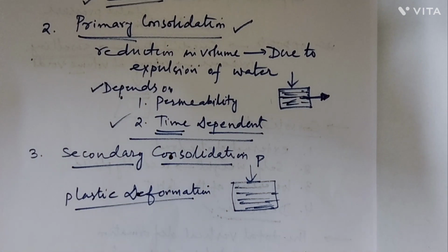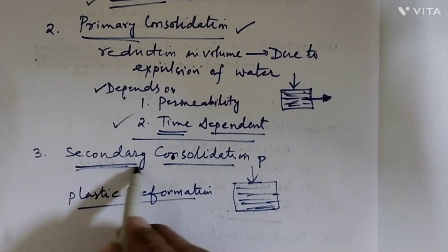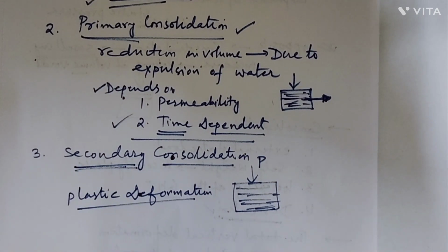It means the soil will get rearranged. The water has been completely expelled. Now what happened? When the load is there, the soil particles will rearrange, and because of this plastic deformation and rearrangement of the particles, there will be further consolidation, which is called secondary consolidation.